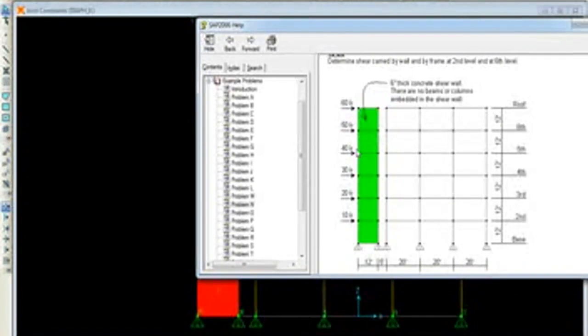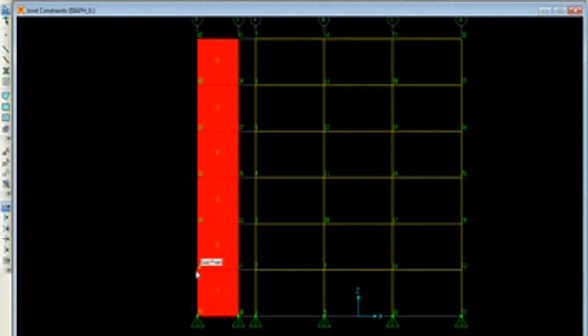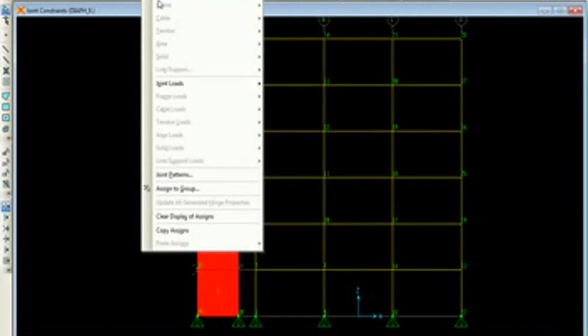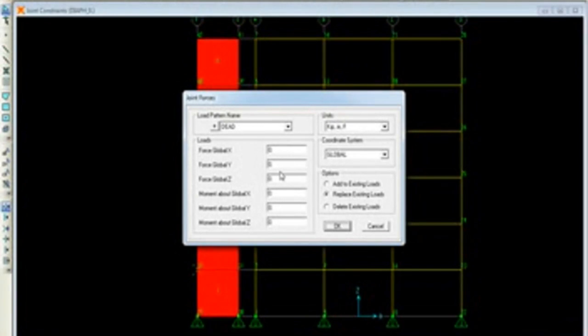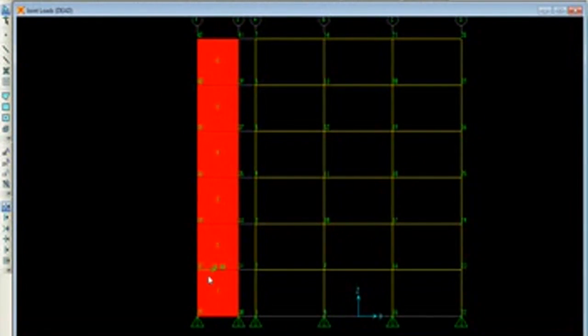At these points you have point loads acting, but I'll give you a simple version. First go to joint 32. Now we can go for assign, joint loads, forces, and you can say in the x direction a 10 kilonewton load is acting on the member. Say okay. Now you see the 10 kilonewtons is acting on this member.